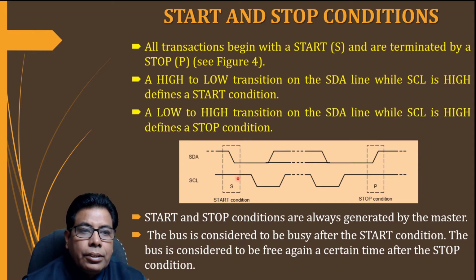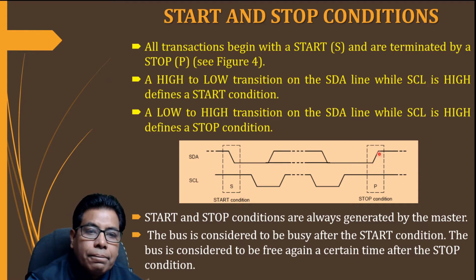The reverse of this, when the data line is going from low to high and again the clock SCL signal is high, that will define the stop condition.